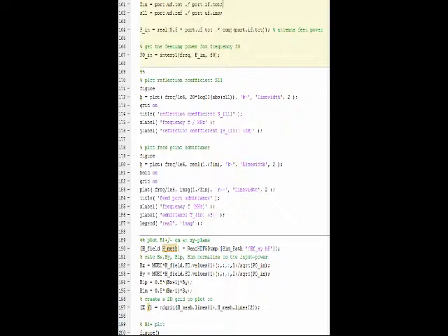We set up the port. Then we have Zin and S11. S11 refers to the reflection coefficient S11, and we will plot it in the following code. P_in refers to the antenna feed power. To get the feeding power for frequency F0, we have P0 in.